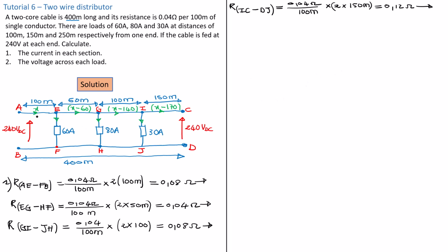So basically the sum of voltage drops across all of these sections must be equal to the difference between these two input voltages, right? So to apply that, we need the voltage drops. Since we know what the resistances are, we can calculate the voltage drop in each of these sections. So the voltage drop on the first section is the current times its resistance.